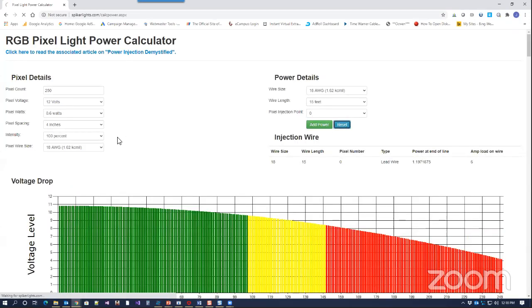And let's change this to 0.6, because all of our pixels today are about 0.6 watts. You'll notice that 200 at 100%, hypothetically speaking, has the potential to draw 12.5 amps. So if the bank on the board is limited to 30 amps, at 100%, you could only potentially use 2 ports, or 3 ports if you want to push it.